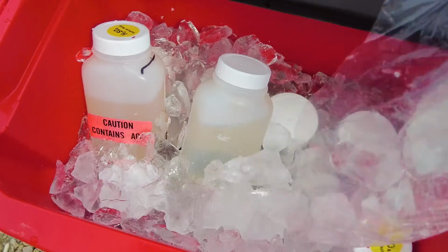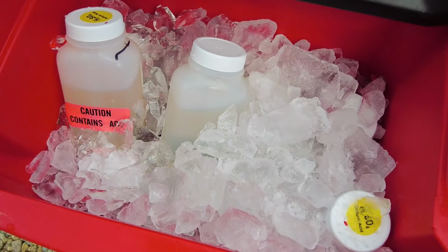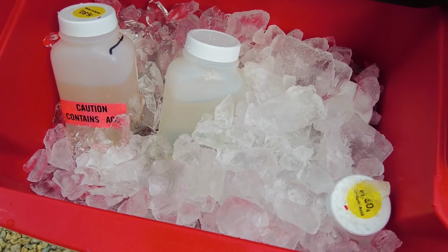The preserved sample should be on ice, although the acidity will keep any bacterial action from happening. BODs, absolutely, you want to keep those on ice. Suspended solids the same way. So treat the samples properly. Standard Methods will tell you exactly how they need to be preserved or kept on their way to the laboratory.